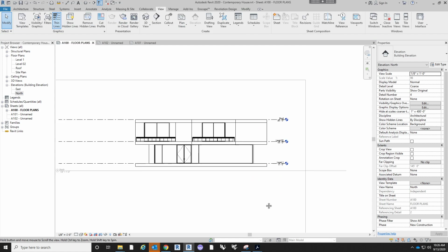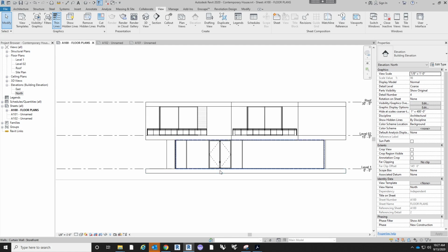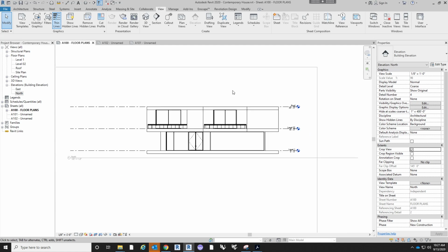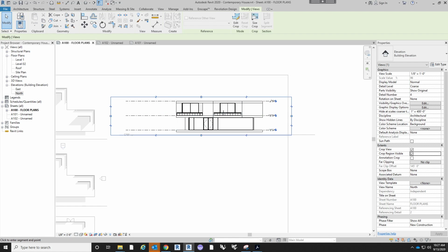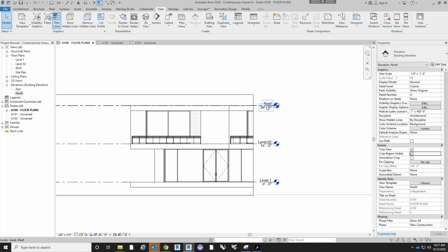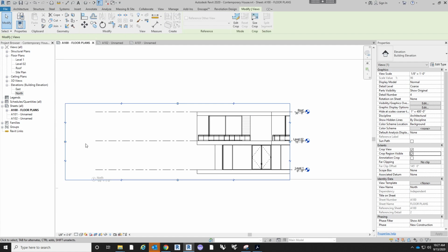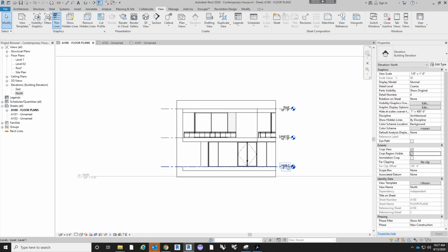Like if you have half of this elevation, you want to do a blow up, right? And you don't want half, or here, let's do it real quick. So let's crop this view. And visibility on. So let's say we cropped it. Now, the visual extent of it will change with the crop. So if we cropped in this guy as well, then it'll change down. But because we've moved it in beyond the actual extents of the level, if we click